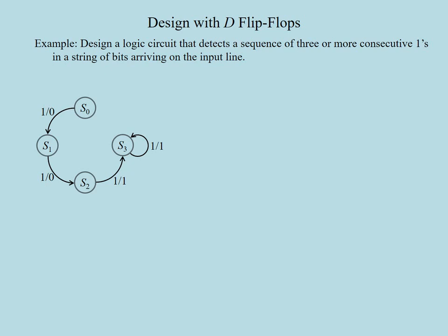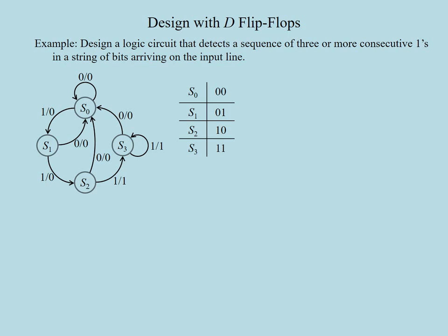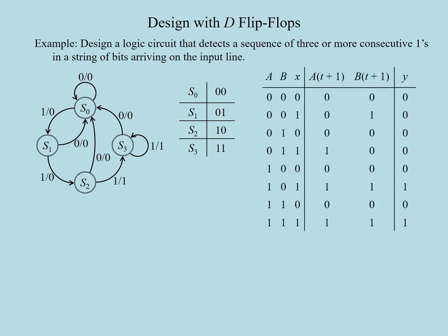In all these states, a transition back to S0 is required whenever a 0 is encountered, meaning that the circuit will start from the beginning to count the arriving ones. This is the complete state diagram. Note that we have 2 transitions coming out of each state, one of them for input 0, the other one for input 1. To do the state assignment with least possible effort, let us denote each state with the binary value of its subscript.